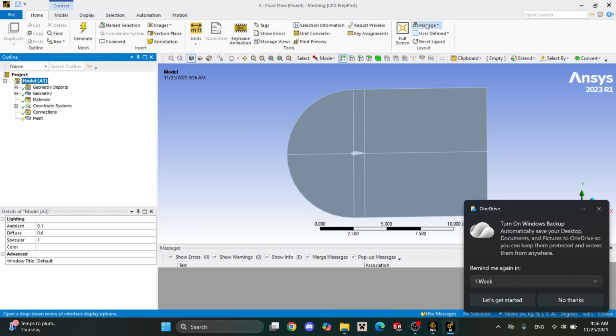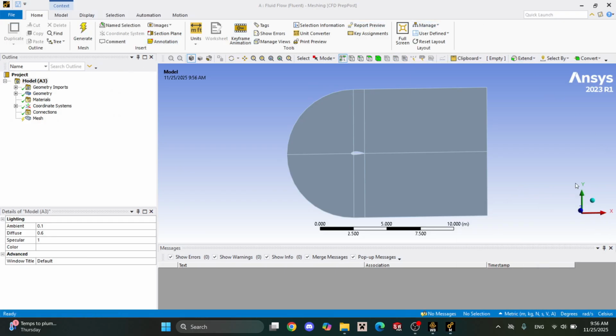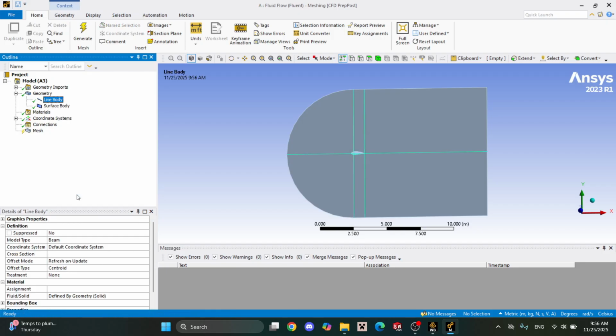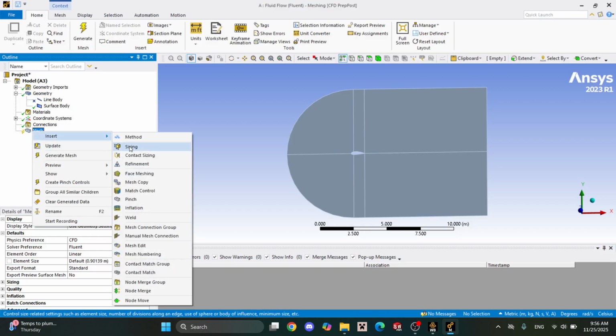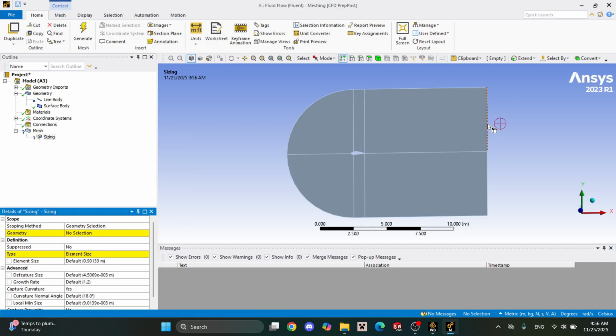All right, so now that it's loaded, I just need to turn these edges here into parameters for sizing the meshes along this C domain. So first of all, in geometry, I'm going to suppress this because that'll just interfere with what I'm going to do.